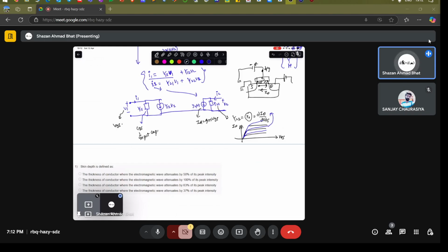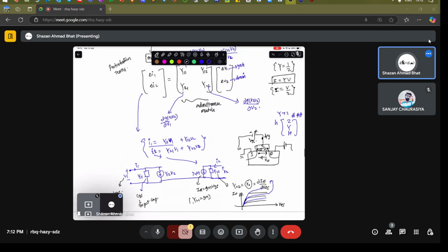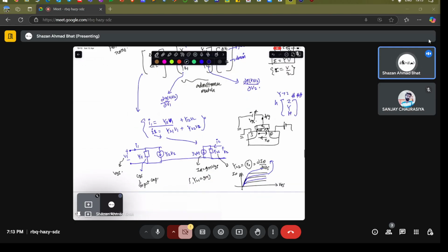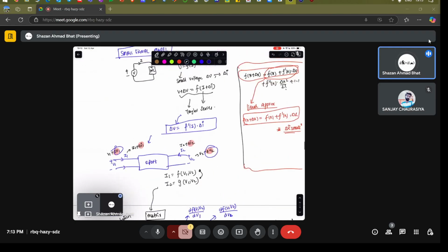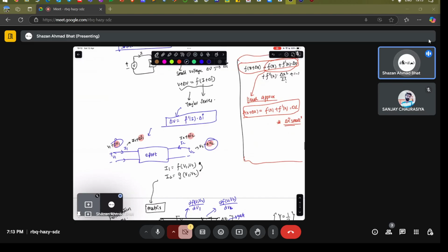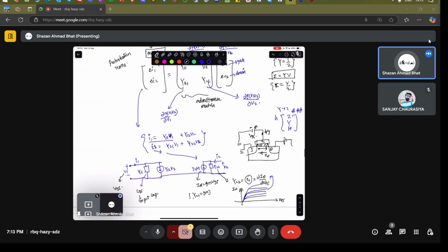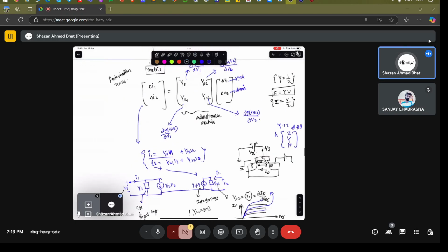That's how you relate these particular models to that of a transistor. And Y21 here is gm, the transconductance parameter. This is just the simplest small signal model of these FETs, how you can convert this equation from writing the Taylor series expansion and going into the circuit part of it.